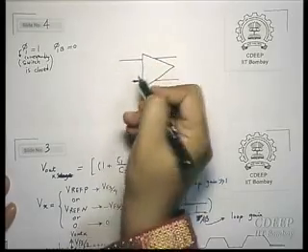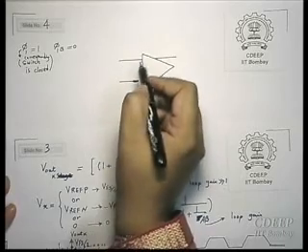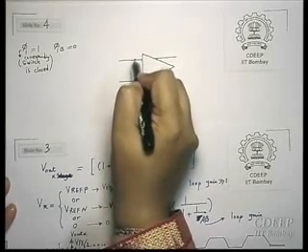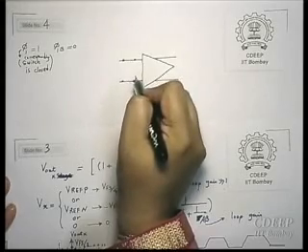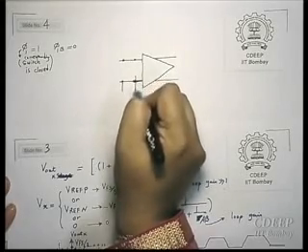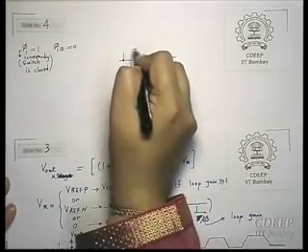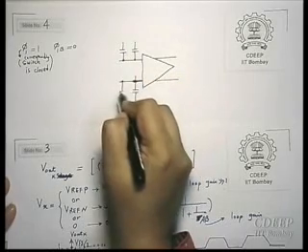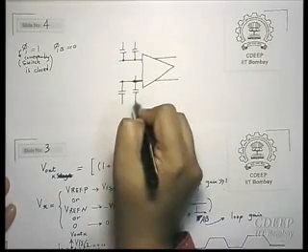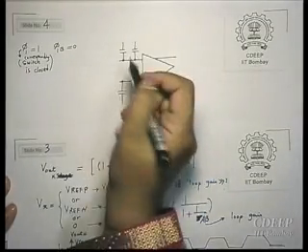So what they are showing in the paper are 2 capacitors with a common bottom plate. That's why the capacitors are connected between the bottom plate. So this is the bottom plate here, and then they are showing 2 different capacitors in this way. So it's the same thing. But they say that when you go to layout, you can make the bottom plate of all of them the same. That's what they are showing in this way.